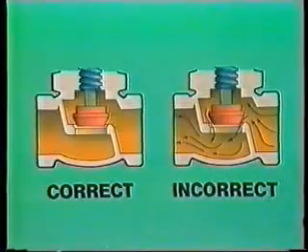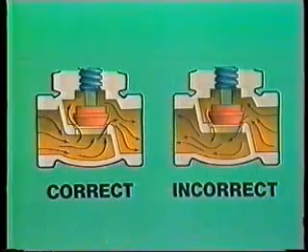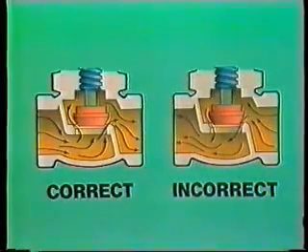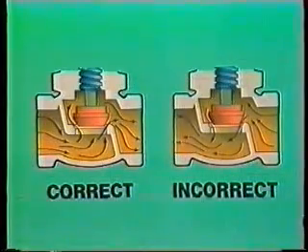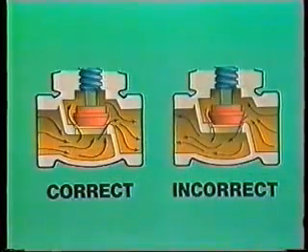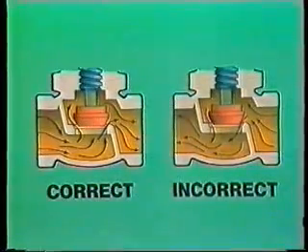A globe valve is usually set up for throttling so that the flow is from below the plug, which tends to open the valve. This provides a more stable operation and eliminates slamming or closing as the plug nears the seat ring. Flow from the other direction would put pressure on the top side of the plug and could close it. Globe valves can be equipped with several types of discs, including the plug disc, the composition disc, and the conventional disc.